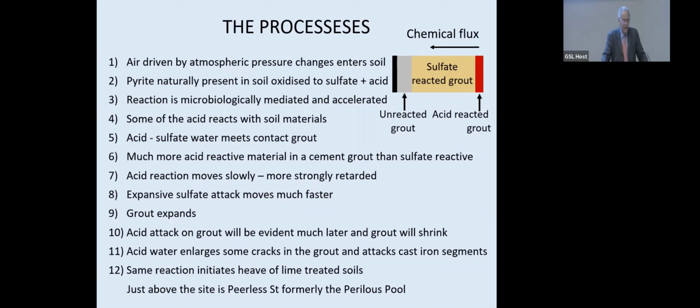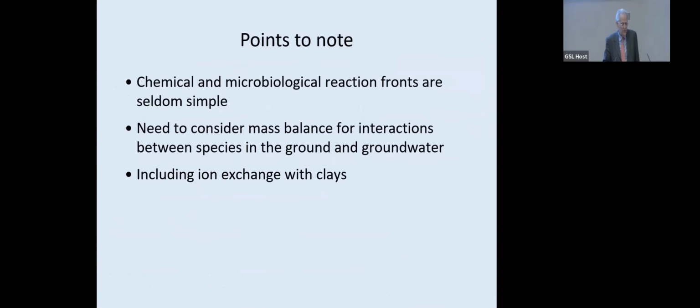The tunnel was then over-tunneled and relined with stainless steel. And we'll come on to the stainless steel in a moment. But that same reaction, the reaction of sulfide oxidation to sulfate, is of course the problem we see with lime-treated soils as well. So let's just begin to pull a few things together.